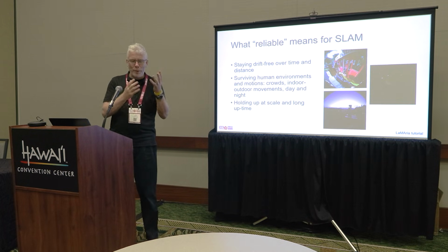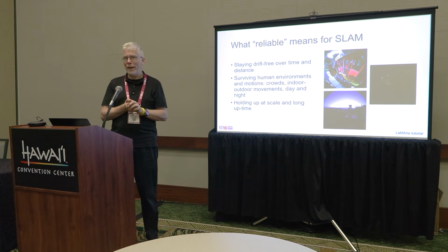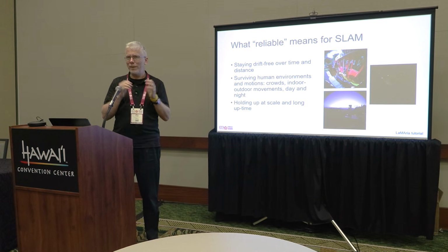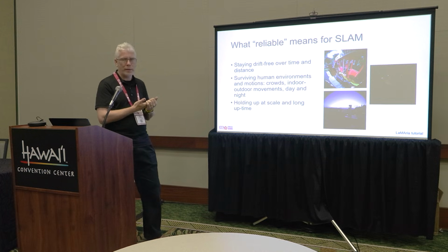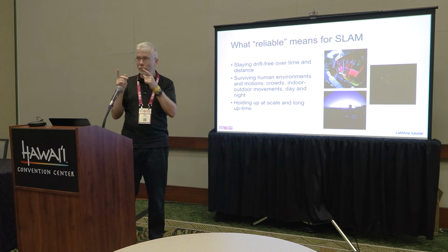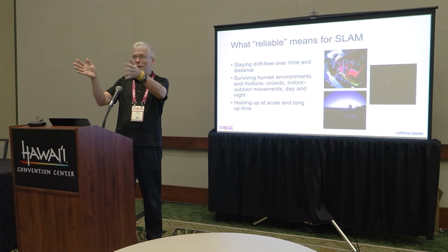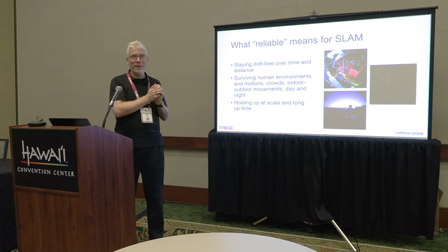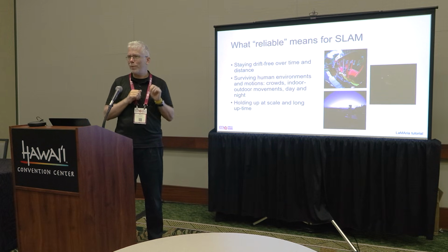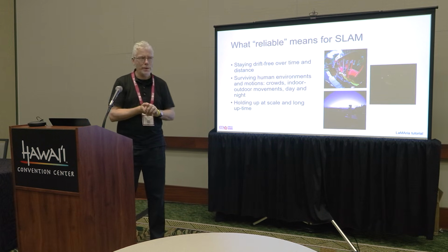Your robots or things like that typically don't have fast head motions. We can turn our head at hundreds of degrees per second. So we can do this. Like this confuses easily systems that have not been developed with taking these things into account. The problem, by the way, if you quickly turn your head, is not only that it quickly changes, especially with VIO, you actually know that you did a large rotation. But the problem is also that the map that I was nicely building up here suddenly is out of view when I look there. And so you break your connection between two maps. And there's issues like this that show up, right?